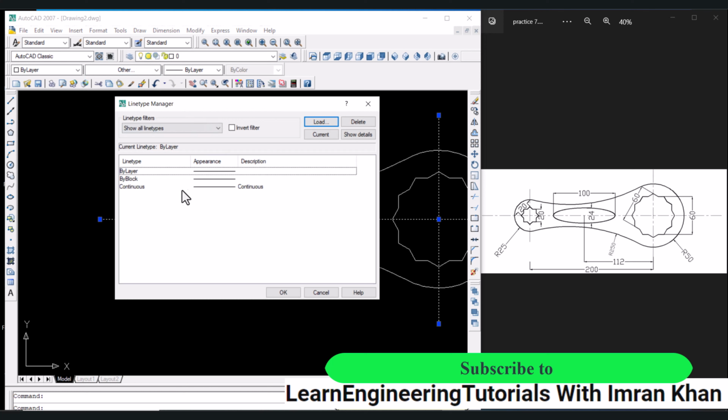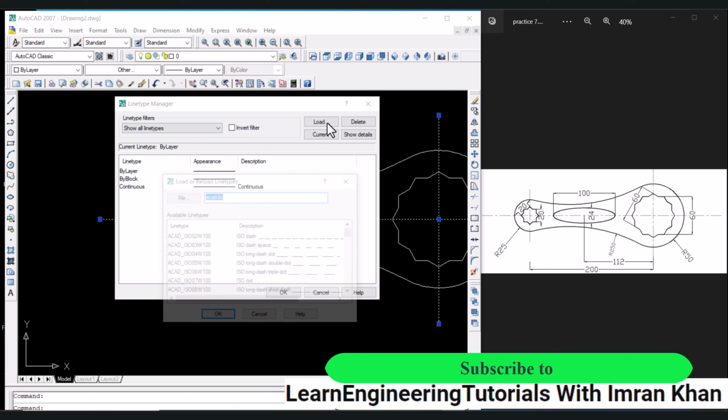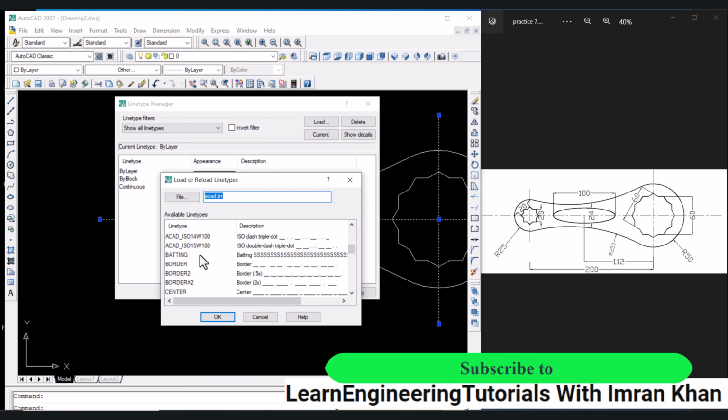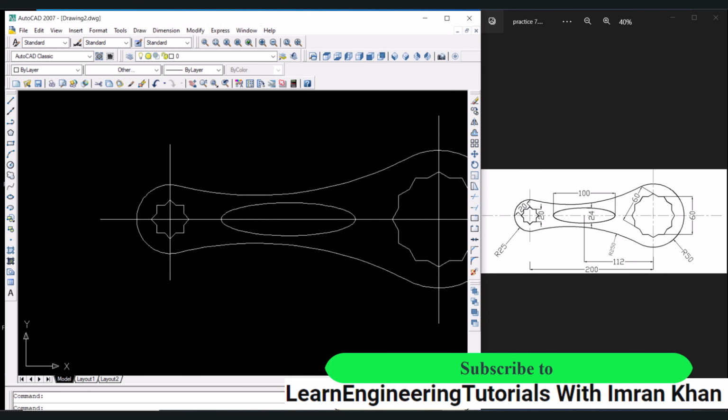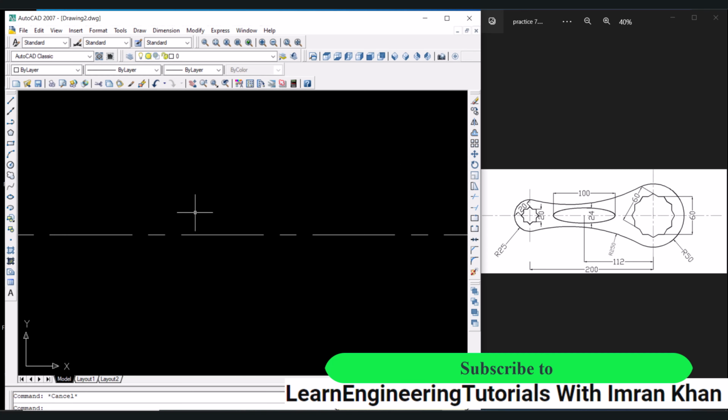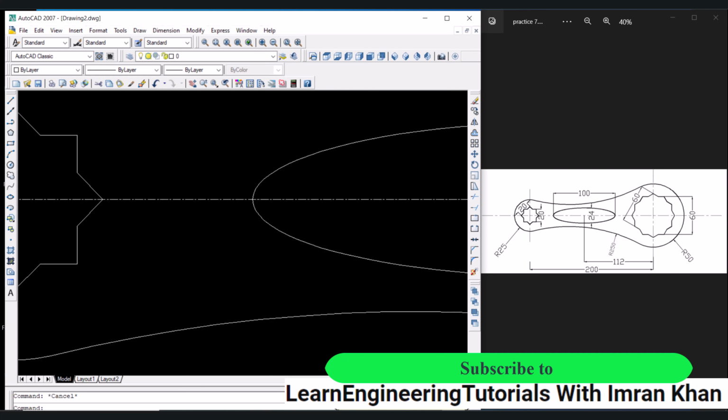So click on other, and here we can't see any other line type, so click on load, look for center, so here we can see center, so click on the center, click on OK, click on center, click on OK again. So now if we select them again and click on center, press escape, and we zoom in, so we can see that the line type has been changed to center line.